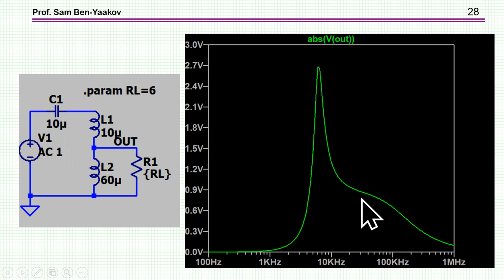In this case, I'm getting the LLC response. This is the gain of 1, somewhere here, which is fine. And then I can have a higher gain, more than 2, which is what I need. I probably could put a smaller capacitor here. But this is not satisfactory because I cannot work at this low frequency. The transformer will not be able to cope with this low frequency.